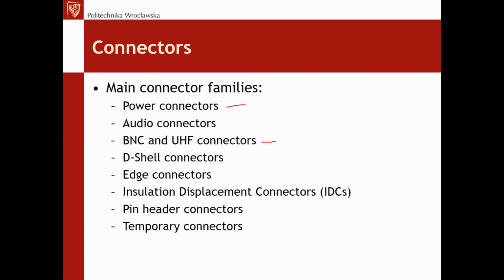Another way of connecting PCBs is the insulation displacement connectors, so-called IDCs. We'll talk about them again next time. Various pin header connectors as well, a large category of connectors, very useful in practical realization because they are very universal and widespread when doing connections for connecting, for example, some sensors, for interconnecting PCBs, for connecting keyboards, LCDs, and so on.